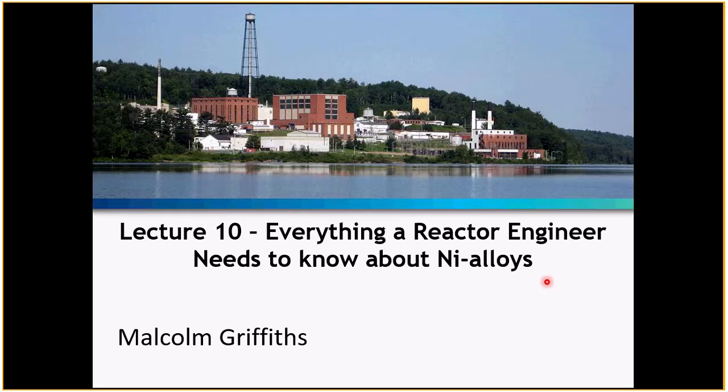Nickel alloys are probably one of the more enigmatic alloys that are used in a nuclear reactor core. When reactors were built, nickel alloys were very popular for certain specialized components, especially springs. So they're standard alloys for standard purposes, especially for spring material. A very good spring material, especially the precipitation hardened nickel alloys, and we'll talk about that in a minute.